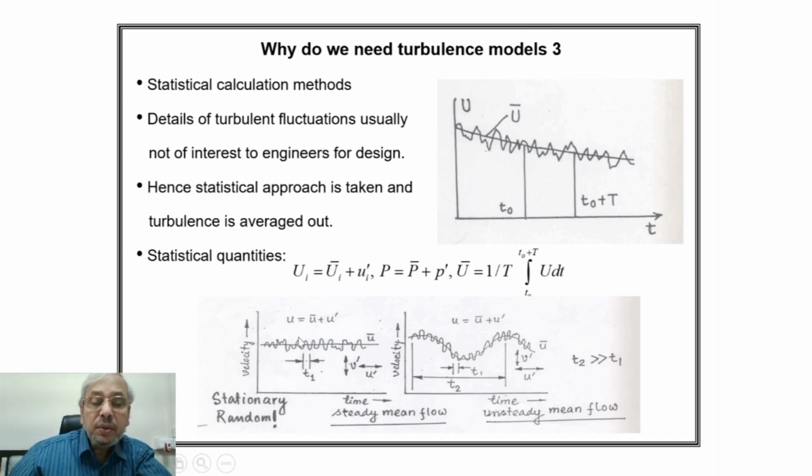Here also we can see instantaneous velocities, and if we average out, we have found U average. It is not a function of time at all. Here also again instantaneous signals versus time we can see, but if we average out, we can see the average velocity is a function of time.